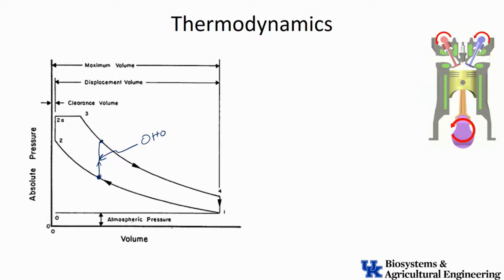Well, a fellow named Diesel, and that was actually his name, where we get the name diesel fuel, said, hey, if we could come up with a way to get those pressures higher in the cylinder, we could get more energy out of this thing and more power. And so he came up with the idea of fuel injection. So we just compress the air, we can allow the pressures to get much higher in the cylinder and get up to this point. And so we get higher pressure, and his curve, what he envisioned, would go like this.